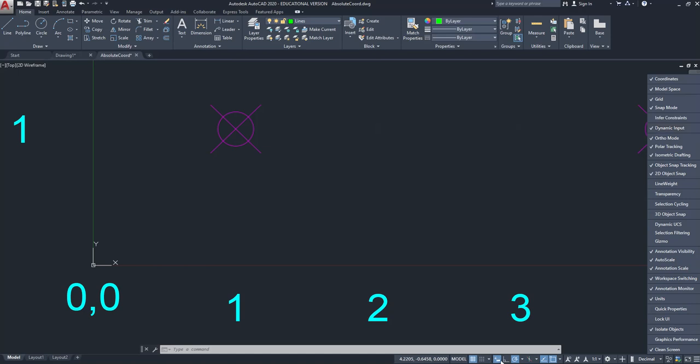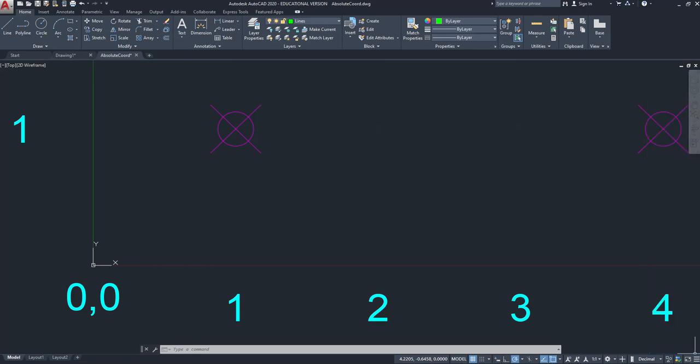And you see down here, this little dynamic input icon turned on, that's what it is. It's a little plus, and it looks like a ruler, but it's actually a little input box, okay? So when I turn it off, it grays out, and when I turn it on, it's blue. And the difference between those two things is this. Do you see how I don't really have anything like was happening before? And when I turn it back on, now do you see all that stuff is back, right? That's the dynamic input stuff, okay? So I'm just going to turn dynamic input off for now.